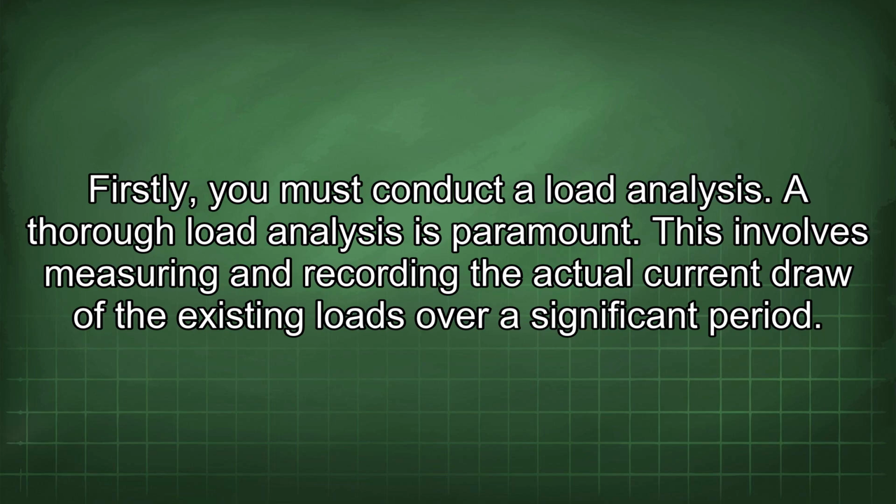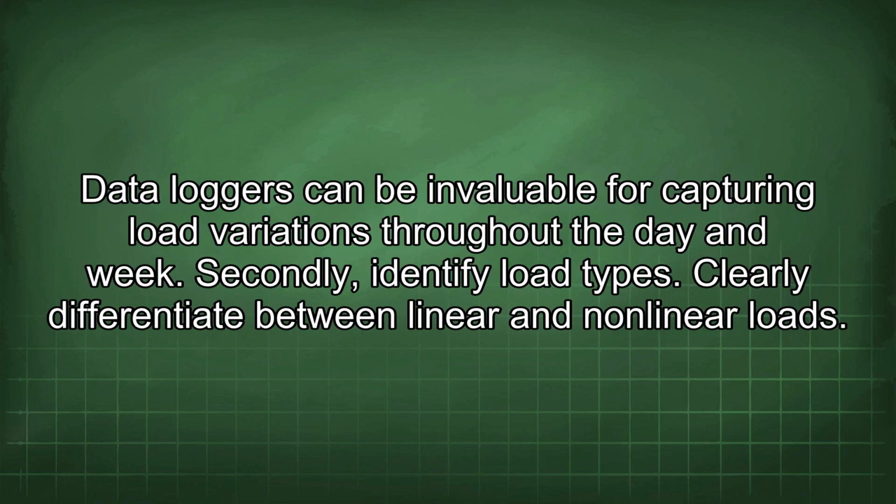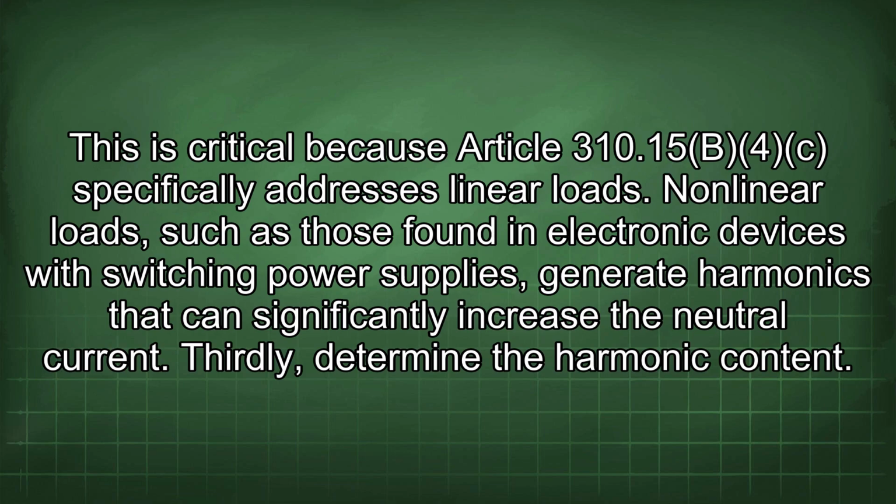A thorough load analysis is paramount. This involves measuring and recording the actual current draw of the existing loads over a significant period. Data loggers can be invaluable for capturing load variations throughout the day and week. Secondly, identify load types. Clearly differentiate between linear and nonlinear loads. This is critical because Article 310.15(B) specifically addresses linear loads. Nonlinear loads, such as those found in electronic devices with switching power supplies, generate harmonics that can significantly increase the neutral current.